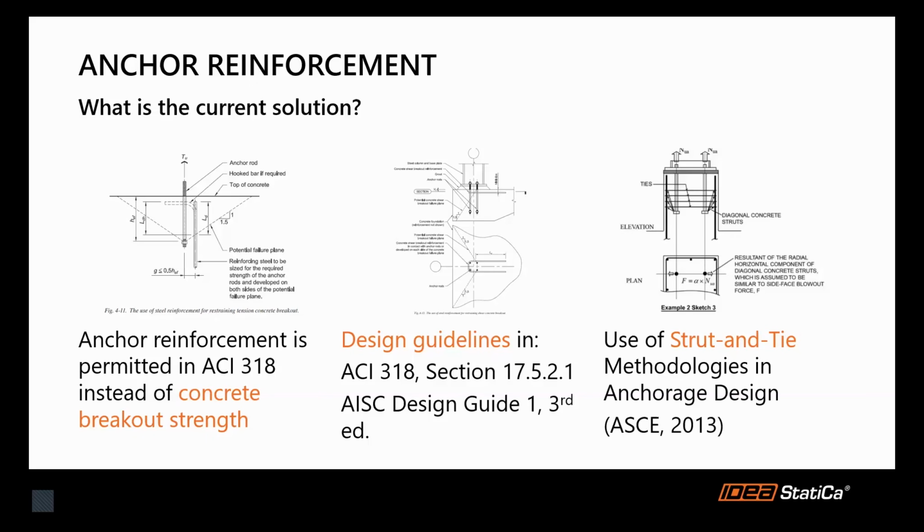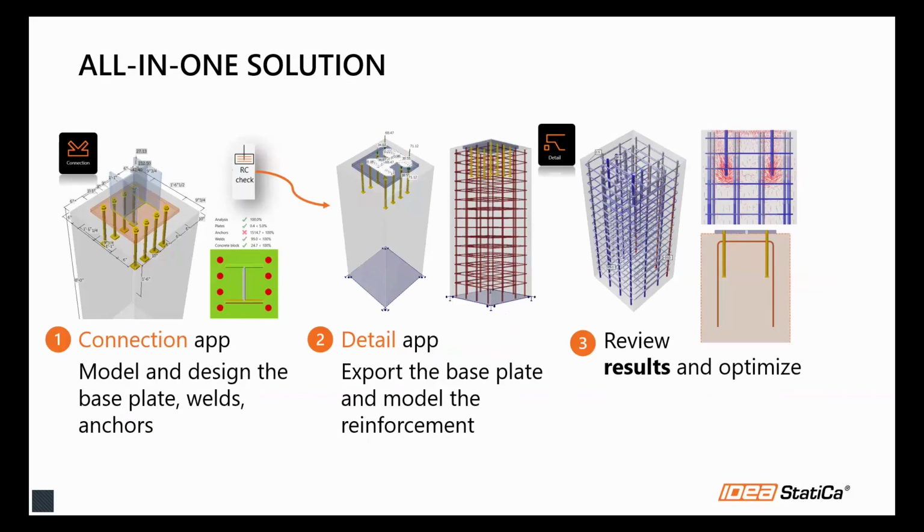So you can basically structurally transfer the shear from the anchors to the foundations. Also, there are some references in the ACI Design Guide 1. And there was also a paper from 2013 discussing strut and tie methodologies for anchor design. So that's what we're going to be able to do now within our detail application. So let's look at how that would all work.